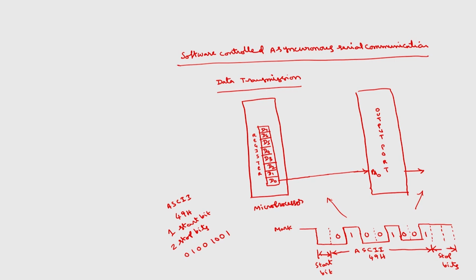First I will send the start bit, and I can write the program later. Then this bit 0 I have to transmit: you take this data into some register and transmit the LSB bit position onto port A, PA0, then you shift this data towards the right and again transmit onto PA0, and you set a counter for the number of bits to be transmitted. After this count is over, we have to stop. This is about the counting operation.